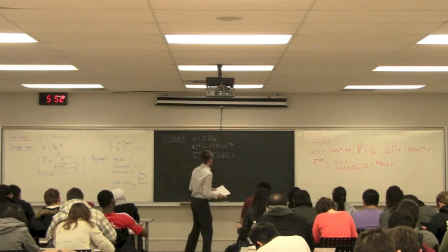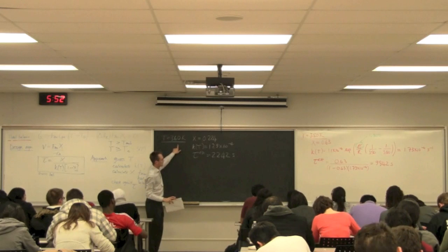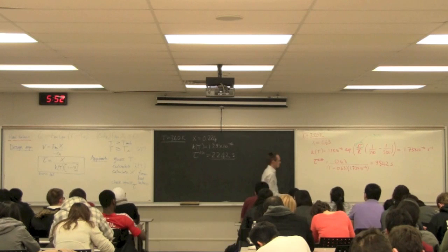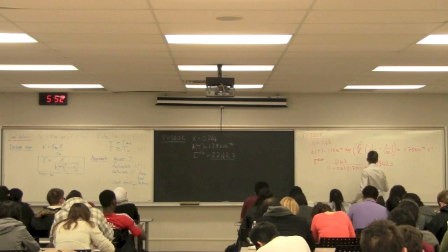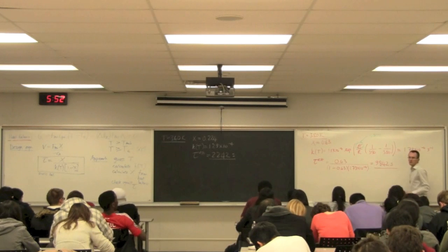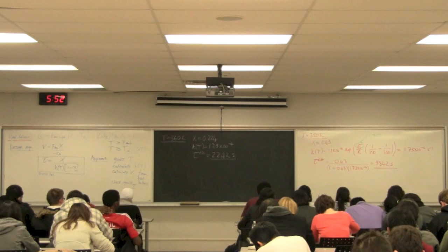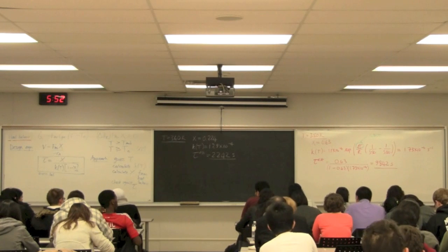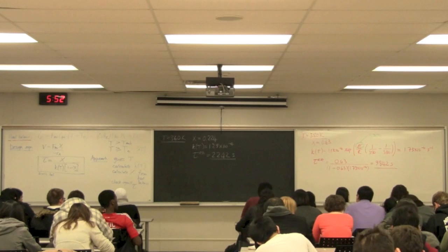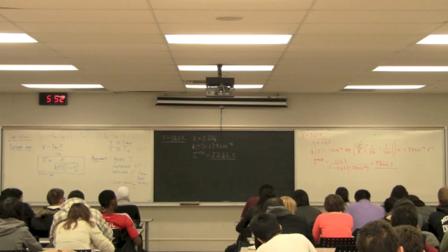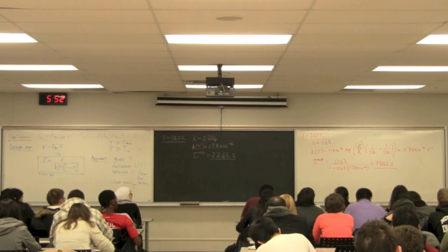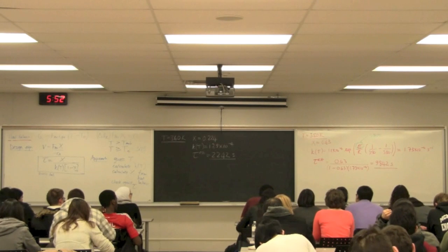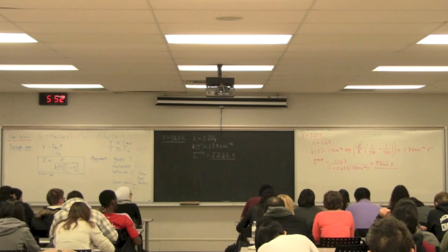So over this 20 Kelvin range, we've caused this residence time to drop quite substantially. And that to me is the biggest indicator that I'm not going to get to this answer quickly. There's tremendous sensitivity here. With relatively minor changes in my guesses, I'm seeing large changes in tau.